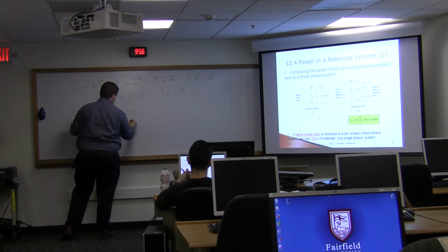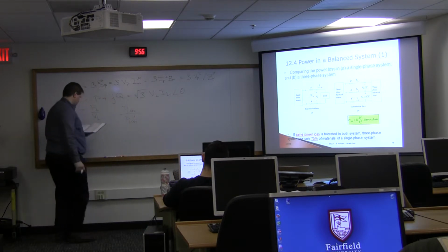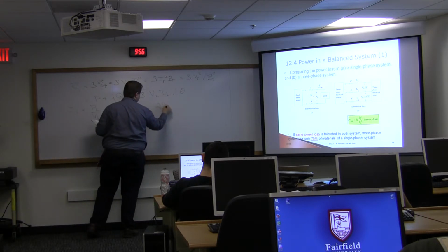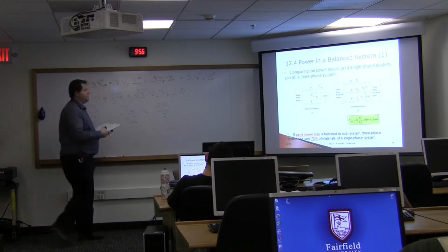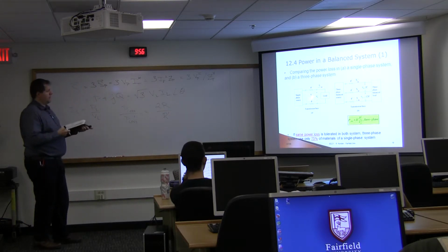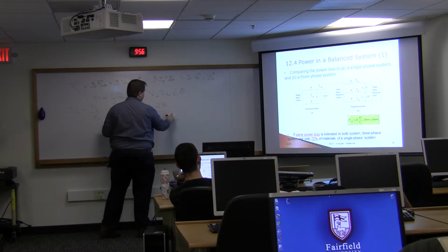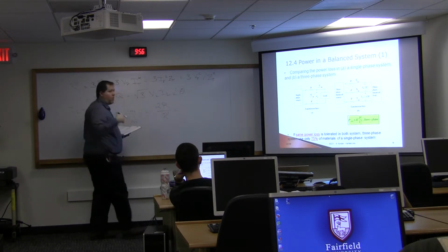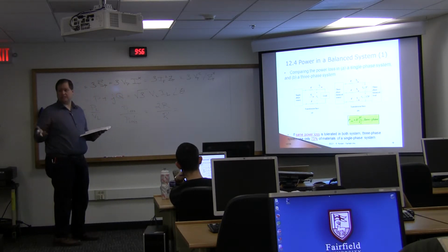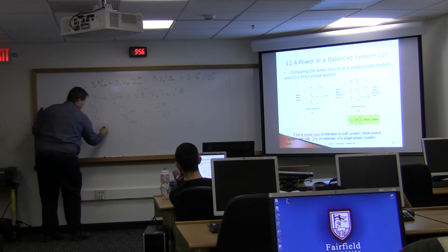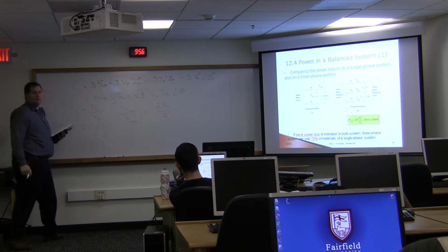And they show us, okay, power loss divided by the power loss prime ends up giving us 2 times the resistance over the resistance prime. So the power loss here, there's 2 R's, and over here, the loss is by 1 R prime. So then we can look at these and remember the geometric form for resistance. Where does resistance come from? Remember that R equals rho L over A.